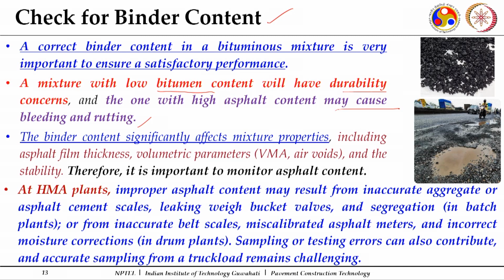So, the binder content significantly affects the mixture properties, and these affect the performance. Along with it, in terms of volumetrics, it will play a significant role. It will change the asphalt film thickness: the lesser the binder content, the lesser the film thickness over the aggregates. Volumetric properties, specifically voids in mineral aggregates and air void contents, get affected, and the stability also.